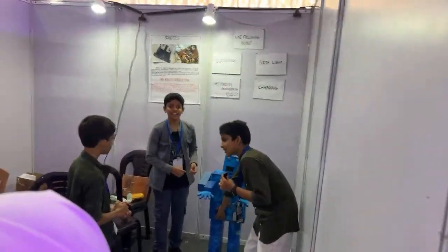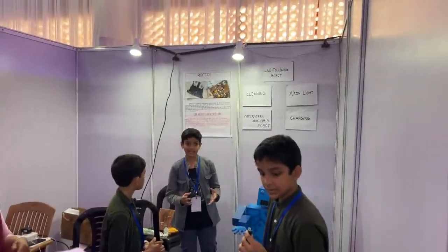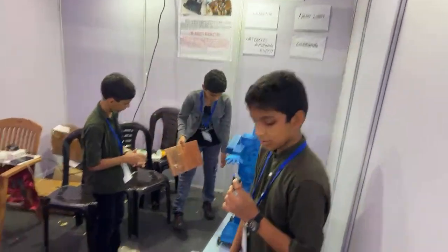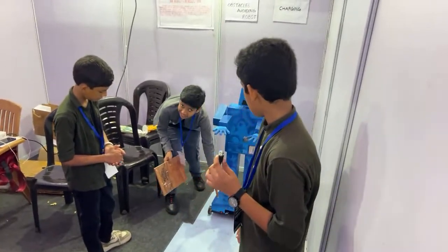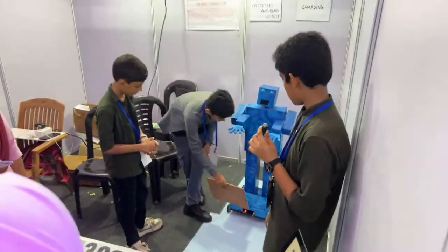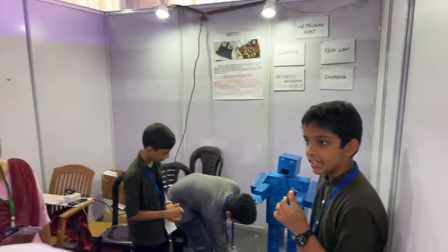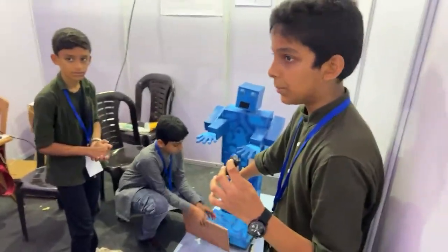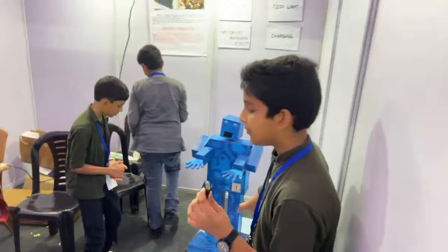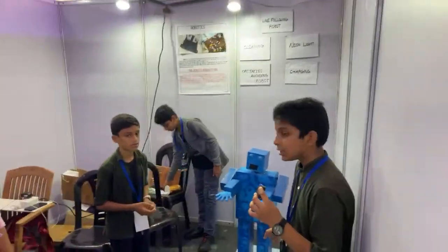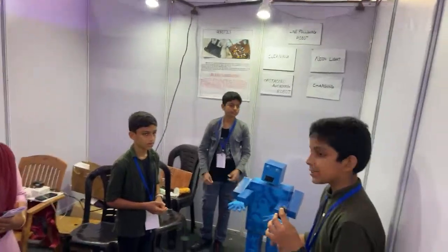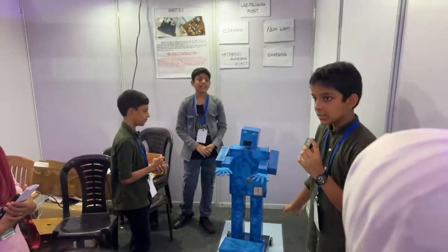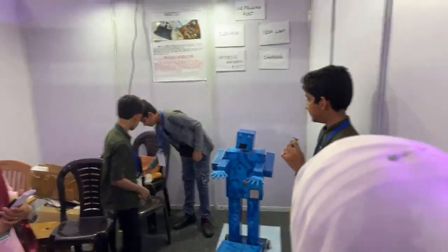As the robot moves, it should detect obstacles and stop. Whenever an obstacle comes in front of the sensors, it will react fast and stop its movement. And in that one, we used the L293D motor driver, 12 volt 100 RPM motors, a switch, a battery holder, and 3.7 volt 2200 mAh batteries.